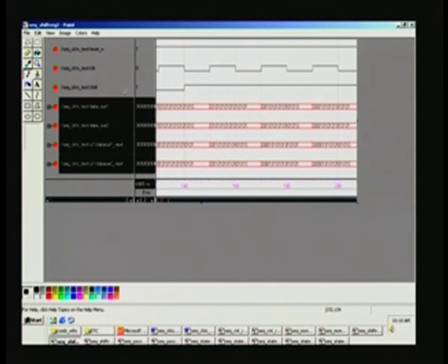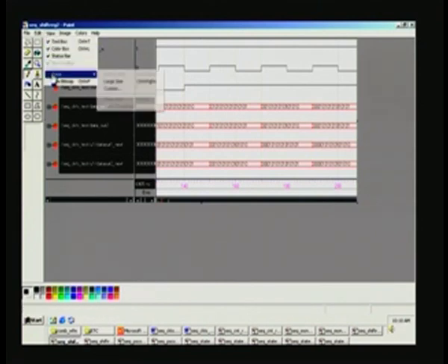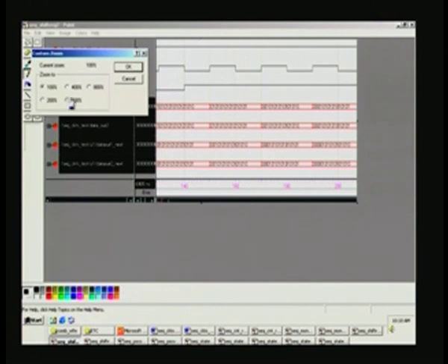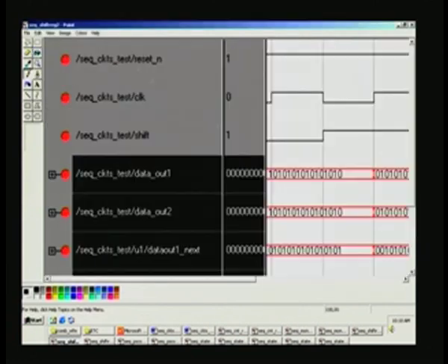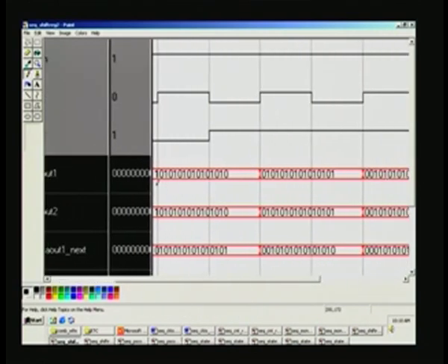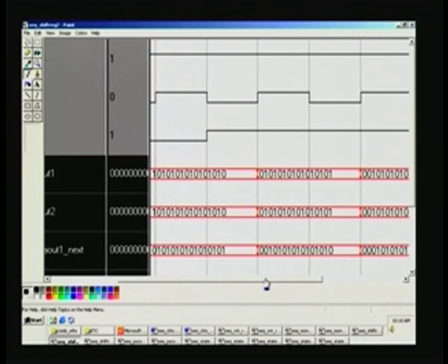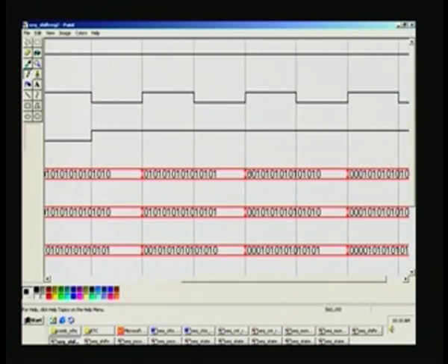So if I once again zoom in here, these are all the data 1, data 2. The first value was 1010, and with the arrival of the next clock pulse it has become 0101, and both are the same. You can have a look all by yourselves and keep on looking at it. See, 2 zeros 1, so all the other bits are there, that means it is clearly right shifting here,